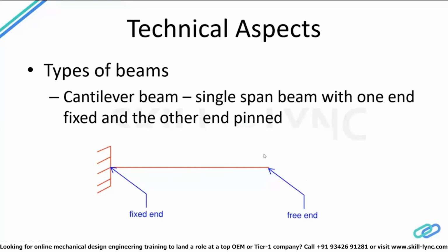So when we say free, that means that joint has no degree of freedom which is locked. But when it's a fixed condition, that means all the 6 degrees of freedom are locked. So whatever load is applied on this cantilever beam, the reactions here will try and equilibrate those forces. So this joint here could develop the translational reactions as well as rotational reactions. So that's what this beam is, and this is really a common kind of beam, which is seen, say, even in canopies.